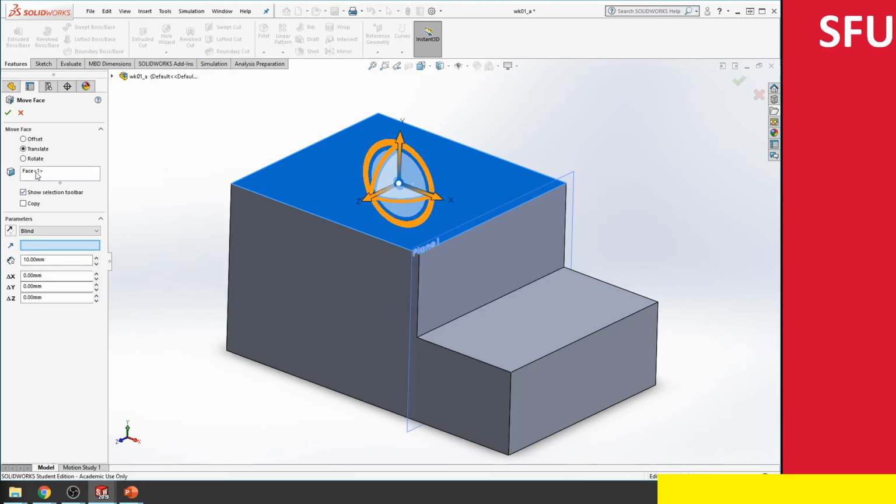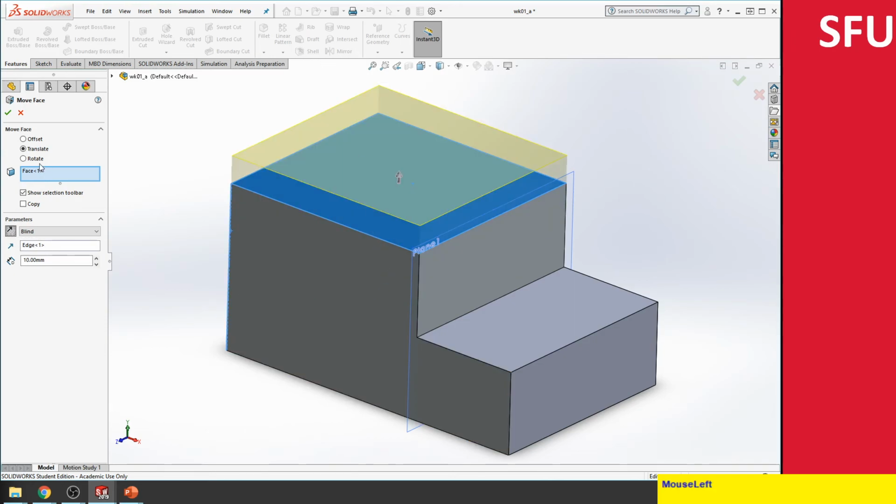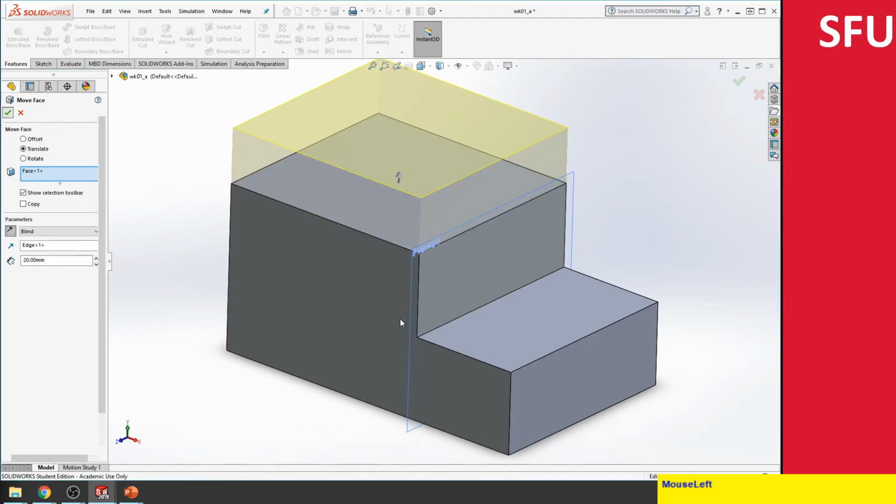Because I selected the face already, that's highlighted in blue. If I wanted to just translate it, it asks which direction I want to translate. So I'm going to select this line to give it an axis. I don't want it to go down. Maybe I want it to go in the other direction. So flip, and then it starts moving up. I can increase the distance and then say OK.